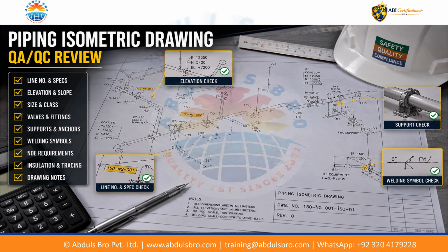What is a piping isometric drawing? The piping isometric drawing is a primary reference for fabrication and installation control. QA/QC personnel verify line identification, dimensions, material specification, piping configuration, fittings, flanges, valves, branch connections, supports and restraints against the approved design. Isometrics are also used to establish joint locations, field connections, and dimensional compliance. Particular attention is given to the latest approved revision, ensuring that fabrication and field installation accurately reflect approved engineering requirements before inspection and acceptance.